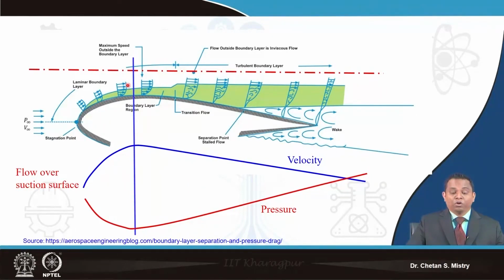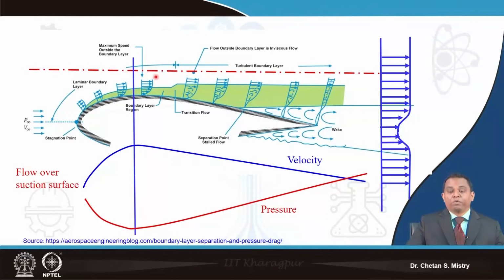Okay. Now this is a very interesting and very important case. On the downside, suppose I use my pitot-static tube and measure my velocity downstream. You will see nearly uniform flow on both sides, but within this region I will be having a deficiency of velocity.